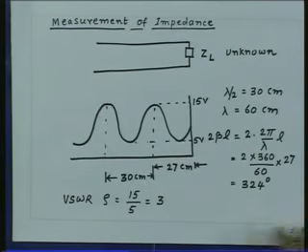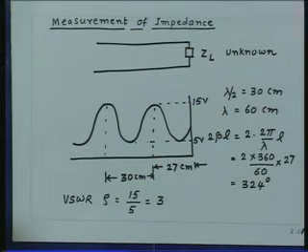As we have seen earlier, the measurement of complex impedance is very tedious at high frequencies because the measurement of phase is unreliable. So, the measurement of an unknown impedance at high frequencies is carried out by measuring the standing wave ratio and the location of the standing wave pattern maximum or minimum. We calculate the unknown impedance.